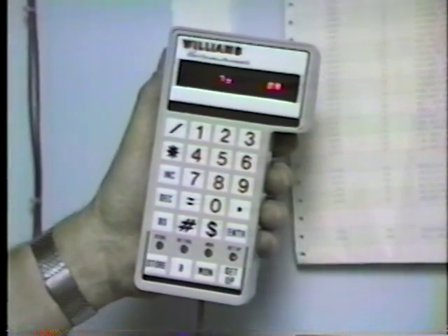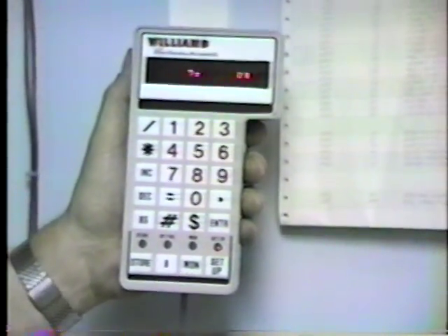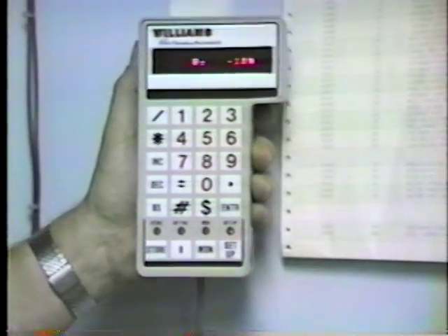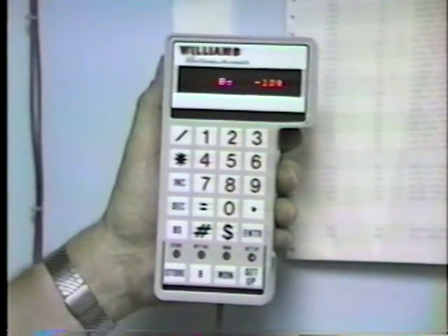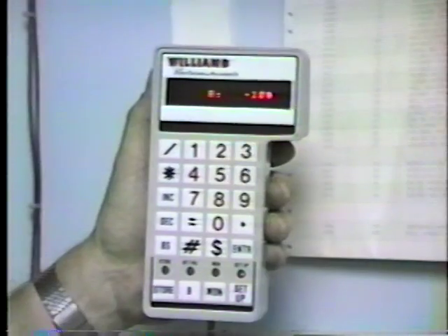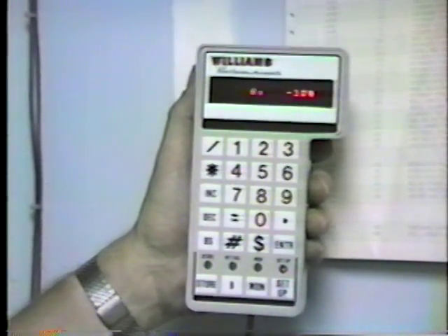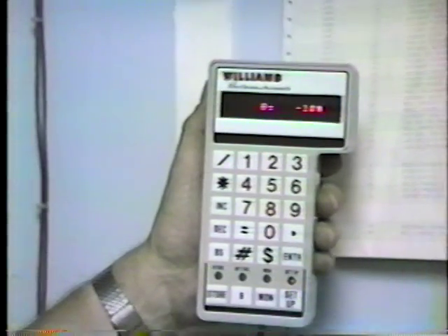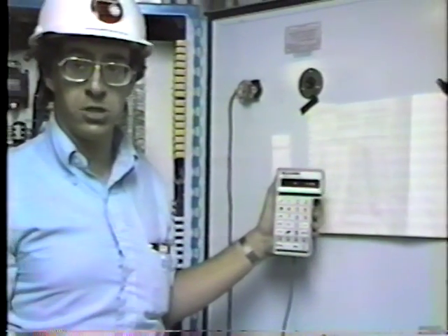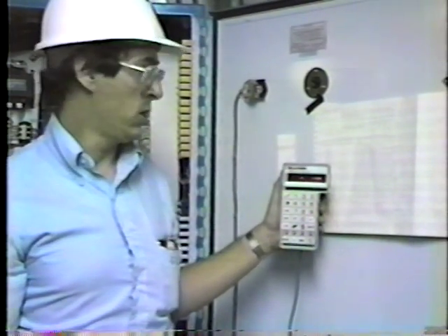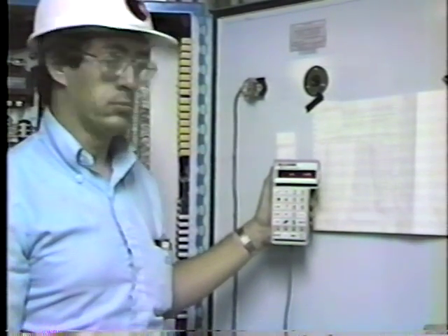Okay. Later on, if somebody was worried about the spinner shutting down, they could increase that to approximately 5% now because we're running at a higher spinner speed. That's right. All right, the next one. Number 8 is the feeder speed maximum decrease. This is just like the spinner, except now that we have our new control algorithm, this tells us the range that we will allow the feeder speed to drop from the calculated target, which is based on boiler demand. All right. We have it set to minus 10%. And again, this wouldn't be changed. Never.